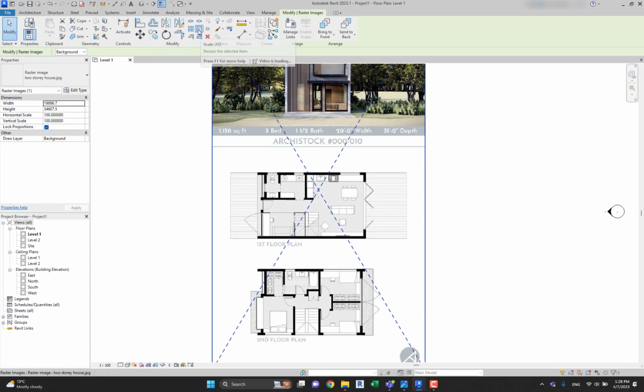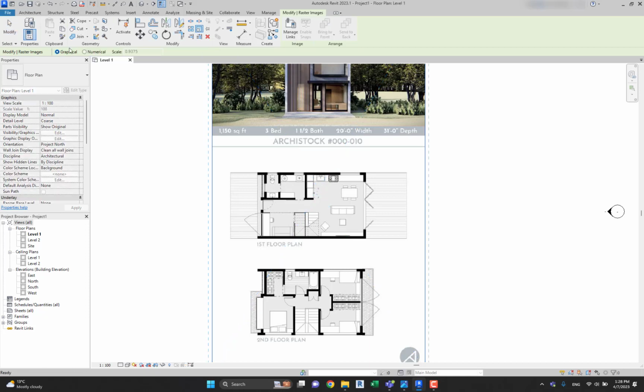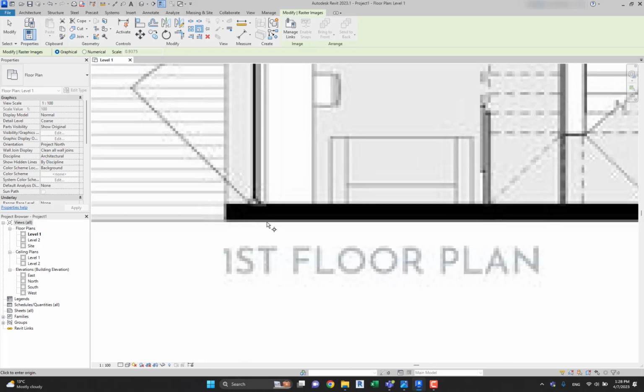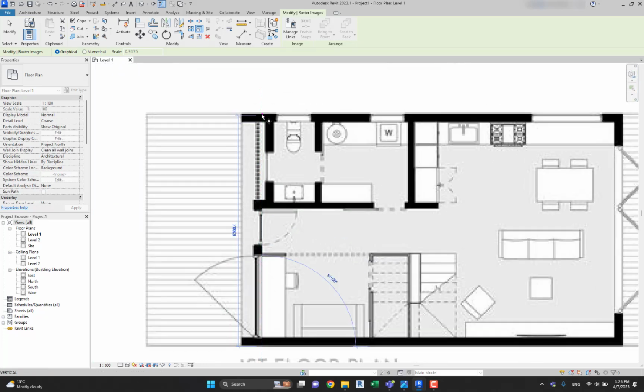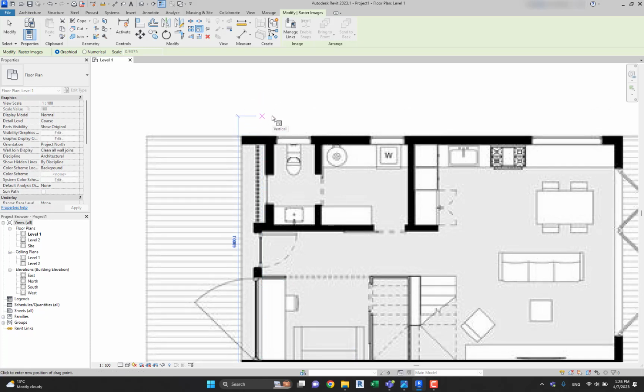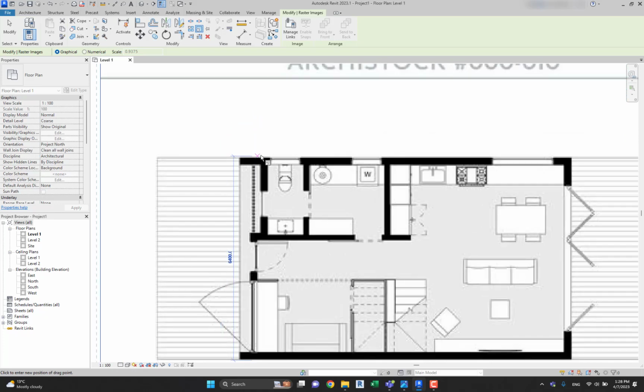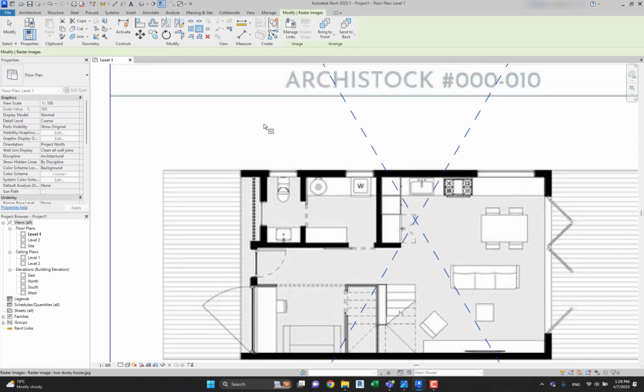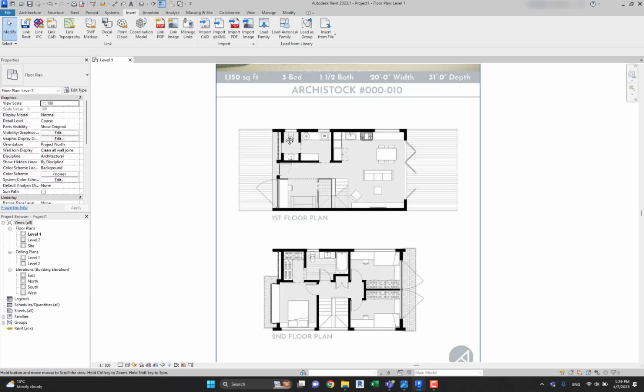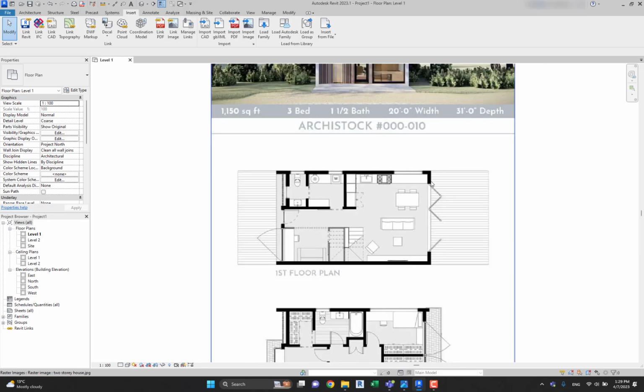The scale you can find it over here. You can use graphical scale or numerical scale. In this case, graphical scale will do the job. So I'm going to select the width of this building. No need to be a perfectionist, no need to be direct on the spot, but approximately. Okay, so let's type it in 6 meters or 6,000. Revit will understand it.